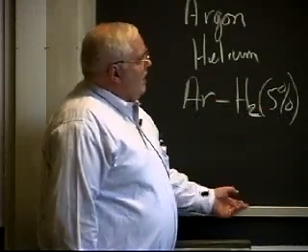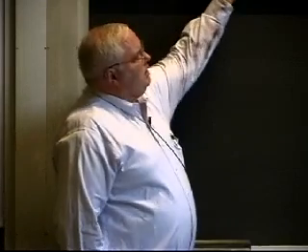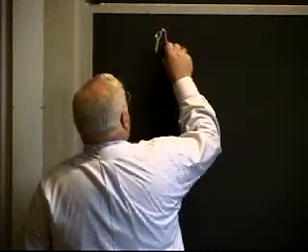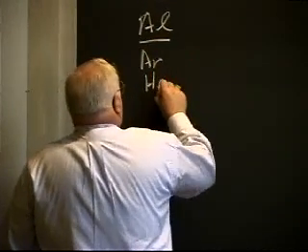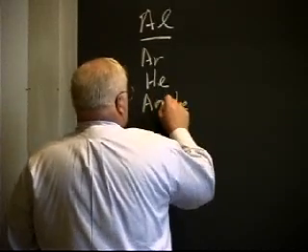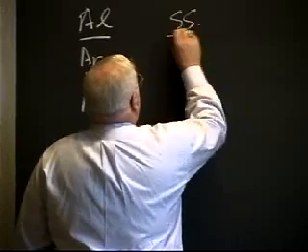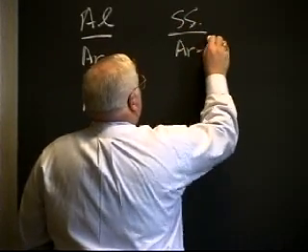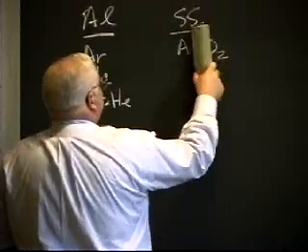It turns out when welding steel, most commonly, we end up using an argon-oxygen or argon-CO2 mixture. So for aluminum, you're going to use pure argon or helium or argon-helium mixtures for your plasma gas. For stainless steel, you can use argon with, well, actually, let's do steel first before I get to stainless steel.